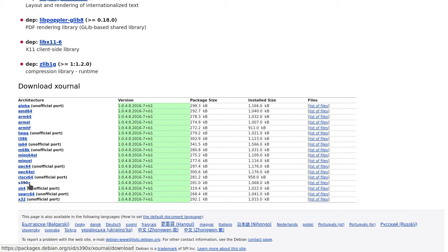7 to 800. Okay, so that's just the power supply of the main computer, and then you have to add to it the monitor, which is not that significant at that point. So let's just say it's 800 watts. Okay. Now you have 5 computers, right? 800 times 5 is 4,000, 4 kilowatts. So with 4 kilowatts, what is the amount of current that is needed?